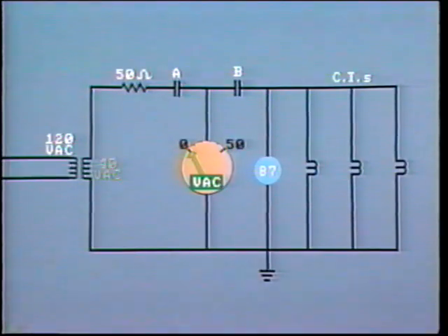Because of the importance of the bus in system operation, some installations include a supervisory circuit, which allows the operator to check the integrity of the bus differential protection circuit. This test circuit applies a low voltage to the relay circuit. When on standby, contact A is closed and 40 volts test voltage is available. Note that this is not sufficient to operate the high impedance relay.